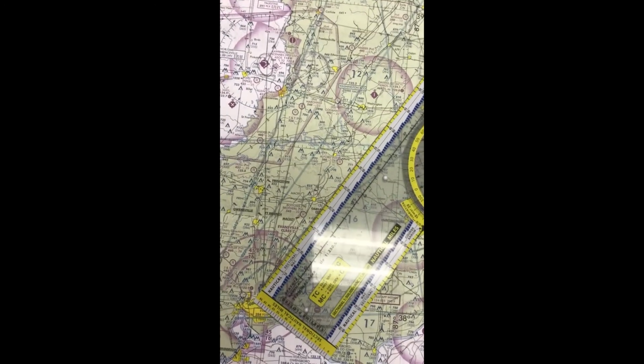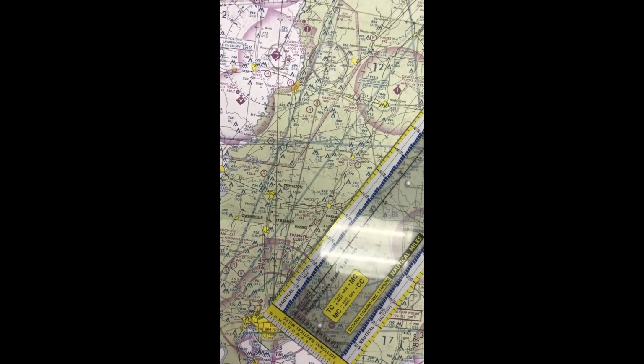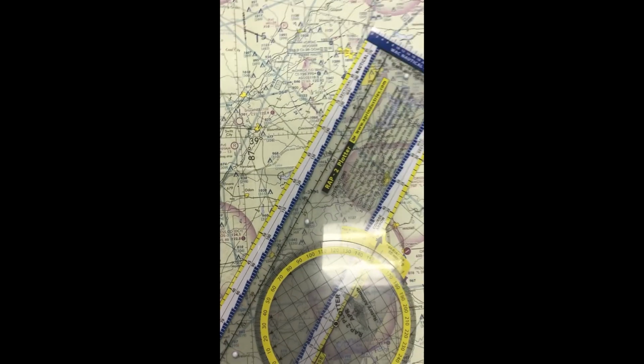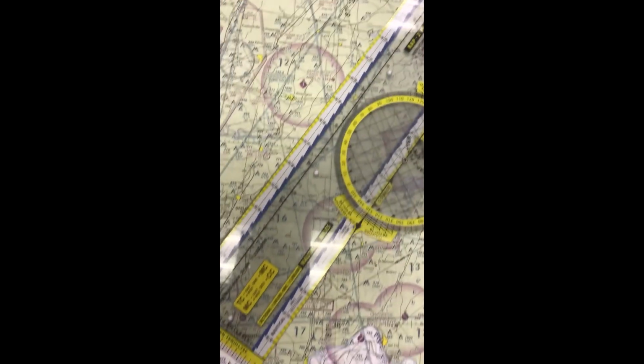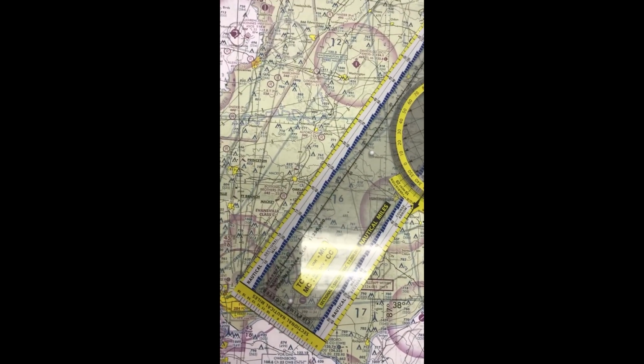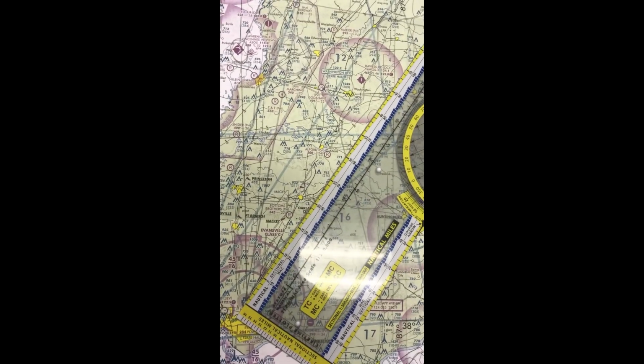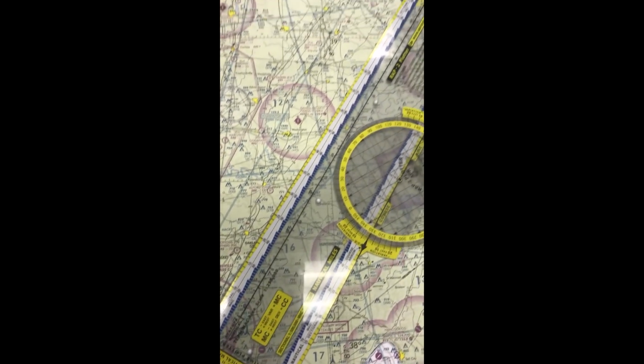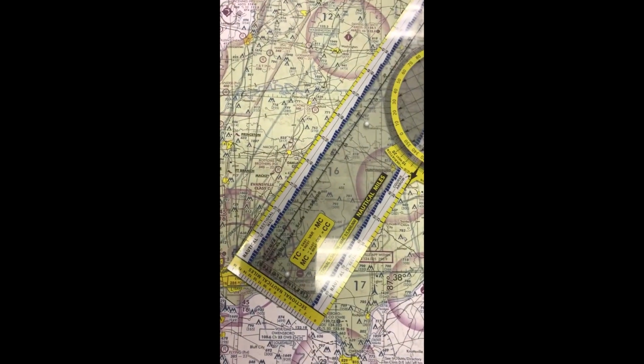Now last time when we did the first one, we just did the one straight leg from Terre Haute to Evansville. So if we did this on this one, we'd have a straight leg from Evansville up there to Monroe County. We can see that would be an 80 nautical mile leg. However, we said for this one, we want to start putting navigation checkpoints about every 20 miles along the route. That'll break it up into different legs, and then every leg will force a new navigation calculation that we need to perform.